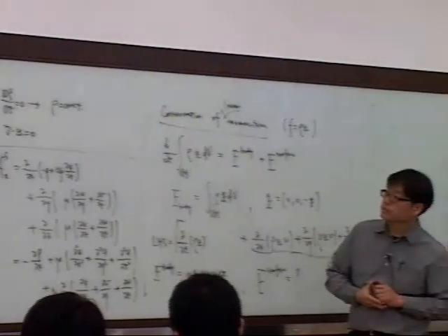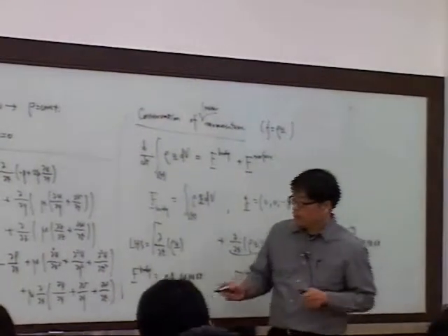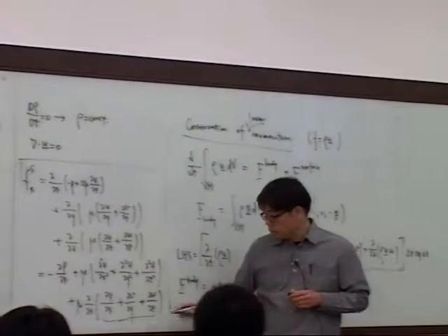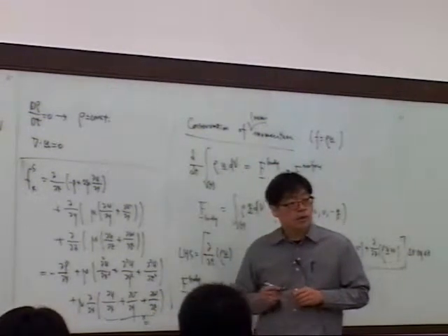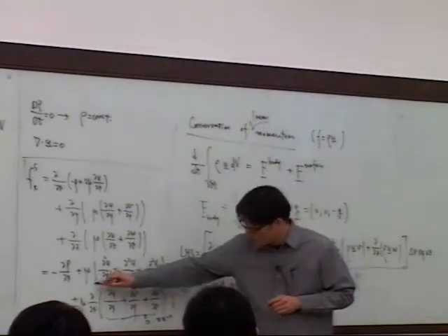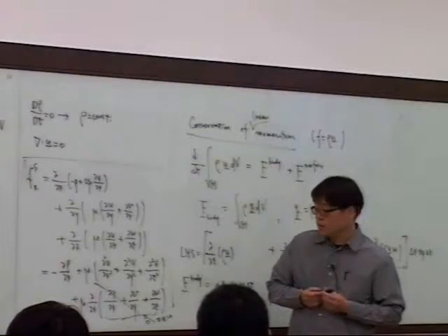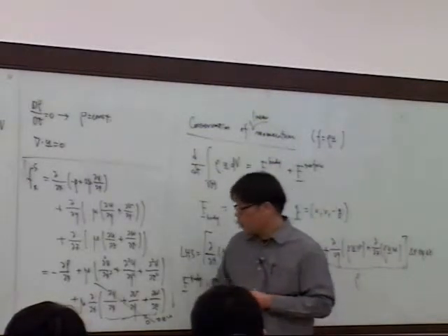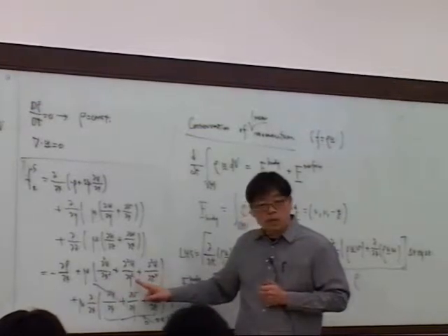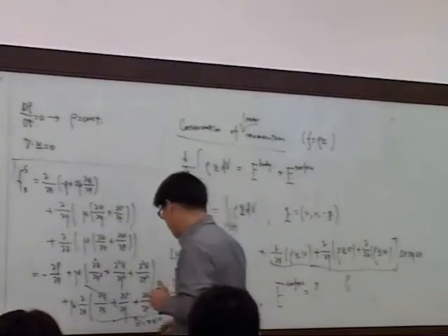Okay? What is this? Continuity equation, which is 0. So this is nothing but the divergence-free condition. So this guy goes away. Okay? So what you end up with is minus dp dx plus mu times the Laplacian of u.